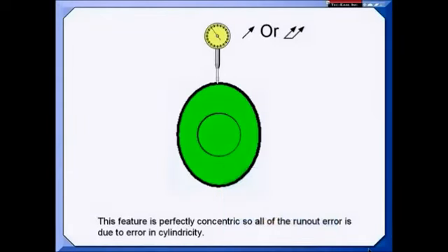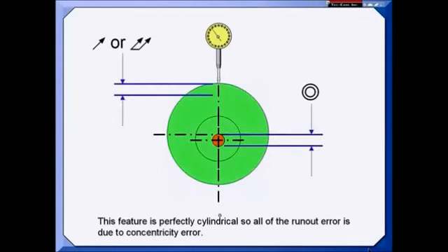Whether you're doing a circular or total runout check, you're using a single point indicator, and you rotate the part and look at the full indicator movement, which used to be called total indicator reading. Concentricity now is defined as the variation that we have in the derived median points. Well, to derive those median points, you need opposed indicator readings to find those median points. And the tolerance zone isn't on the surface like it is with runout, it's in the middle.